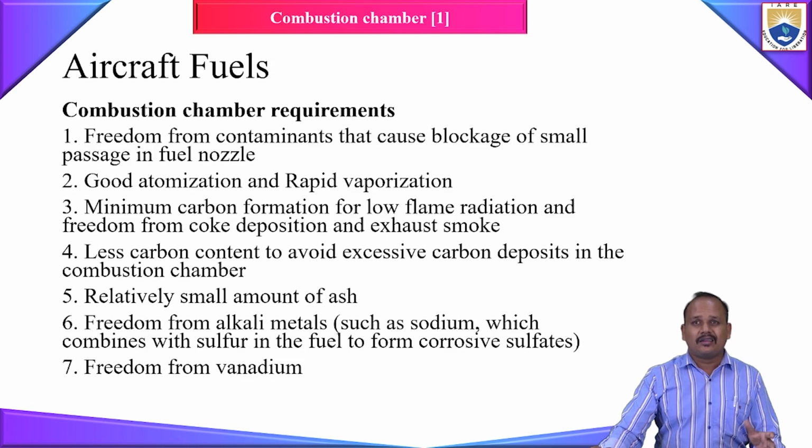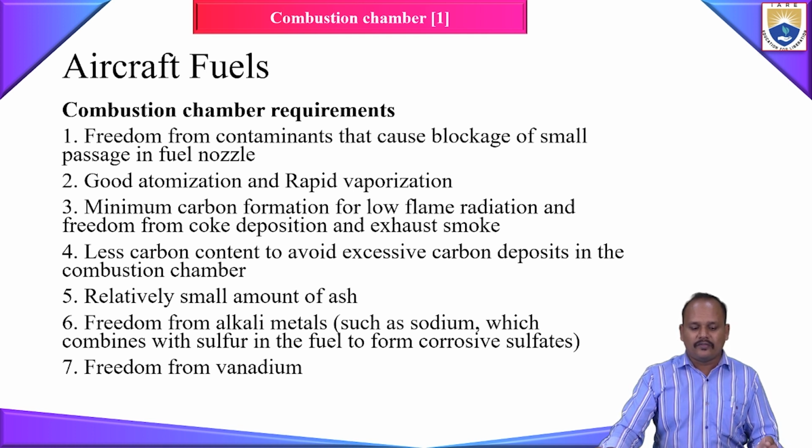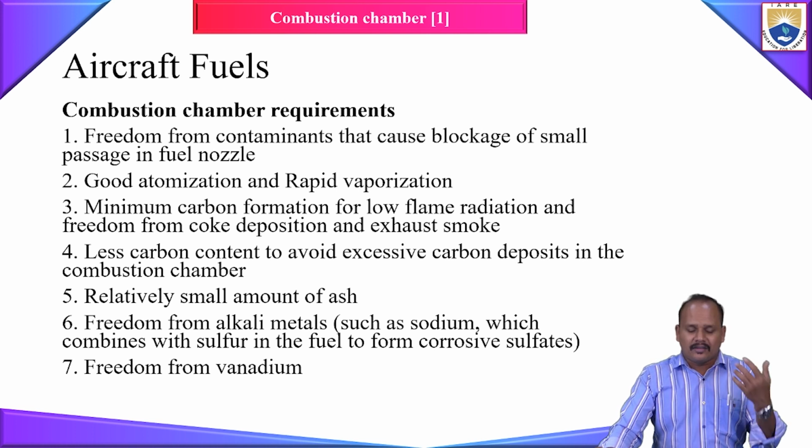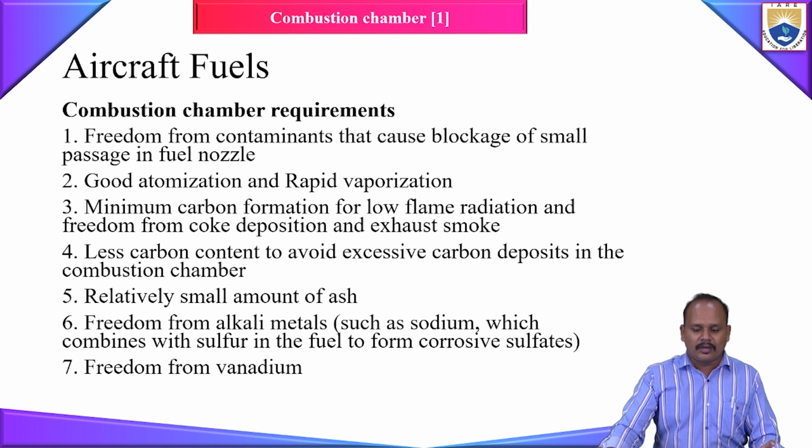Next one is the combustion chamber requirement. So what is the combustion chamber requirement? First of all, your fuel should be free from contaminants that are going to cause blockage of your fuel nozzle or fuel injector. The hole in the fuel injector is very small. If you have external contaminants, what is going to happen? It is going to block your passage, which is going to prevent fuel from coming out.